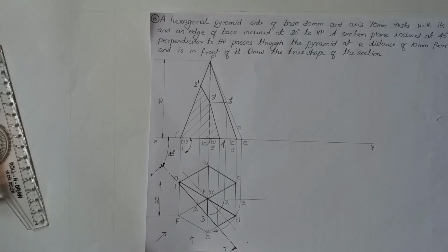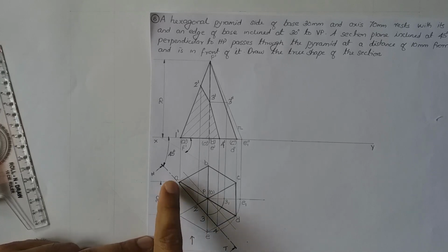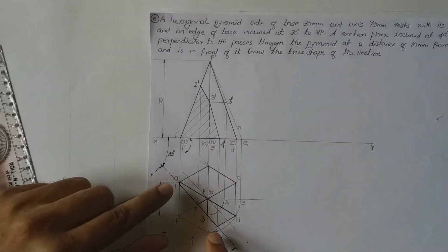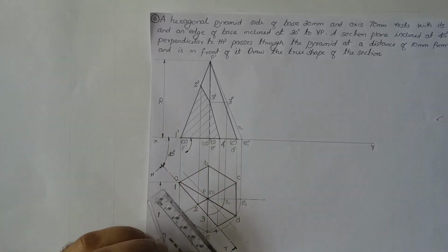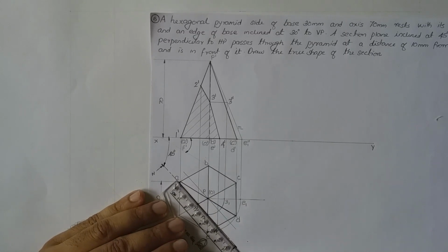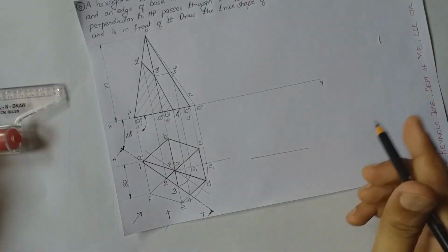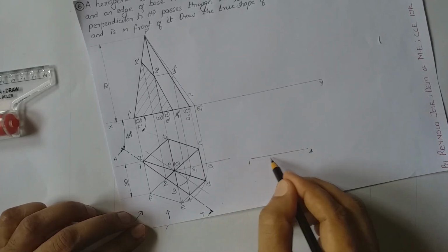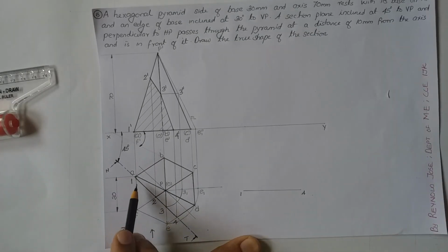So what is the procedure for drawing the true shape? We shall reconstruct 1/4, which is our section plane passing through the solid, separately to another side of the same diagram. We shall straighten this line 1/4 and draw it to the right hand side. We shall measure 1/4. It is approximately 51. Whatever value you are getting, you take it as such. So this point is 4 and this point is 1. So the total distance is 51. We have taken it from the previous diagram. So the length of line 1/4 is the same as that of this 1/4, which is 51.